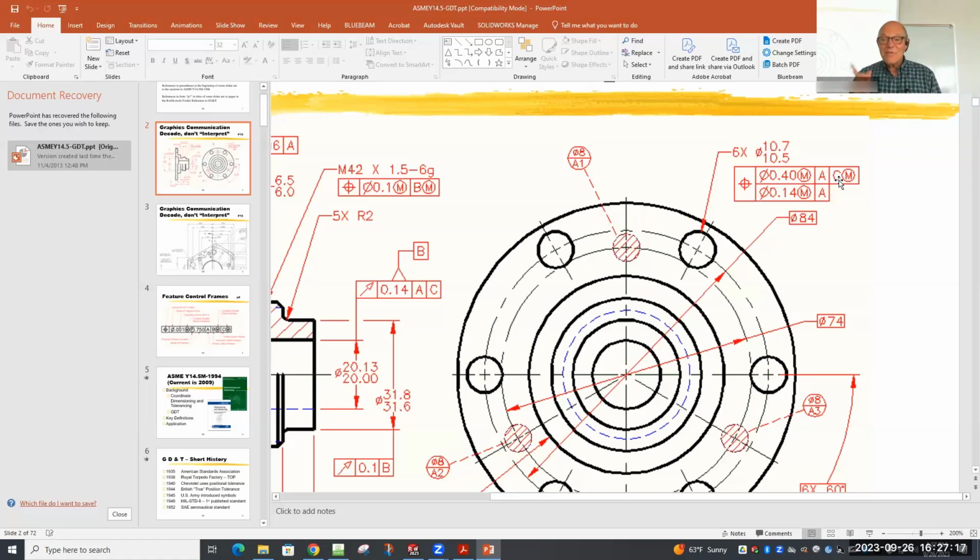If you ever see a drawing with 4 datums referred to in that frame, the person has no idea what they're doing. And I mean, no idea what they're doing. There's no such thing as a 4th datum. There's nothing left to control. Primary is 3, secondary is 2, tertiary is 1. That adds up to 6. That's it. There's nothing left.